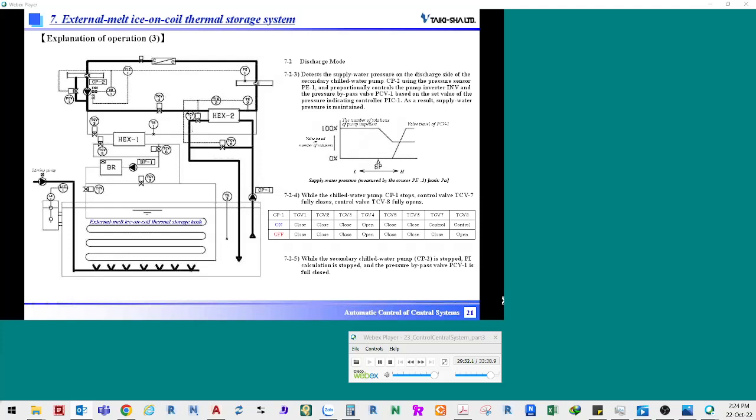If the pressure is beyond the set value, the number of rotations of the pump motor is respectively reduced. The pump has a minimum motor rotation number to secure a minimum flow rate. If the pressure increases while the pump motor is rotating at the minimum rotation number, the pressure is controlled by opening the pressure control valve PCV1.